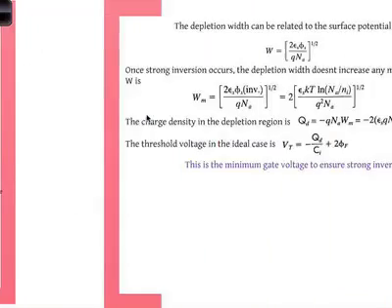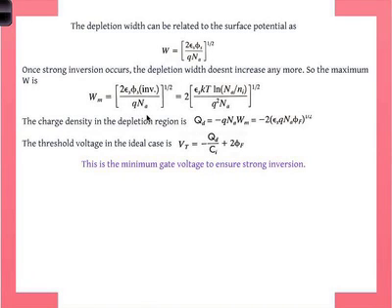Okay? So the threshold voltage, in other words, is the potential that you apply needs to do 2 things. It needs to create the maximum depletion region beyond which the depletion region doesn't increase, and it needs to bend the bands to create strong inversion. So you need to accommodate for these two things. That gives you the minimum threshold voltage. Okay? That's the idea. So this is a very important parameter, and in a transistor design, again, device designers spend a lot of time trying to optimize this.